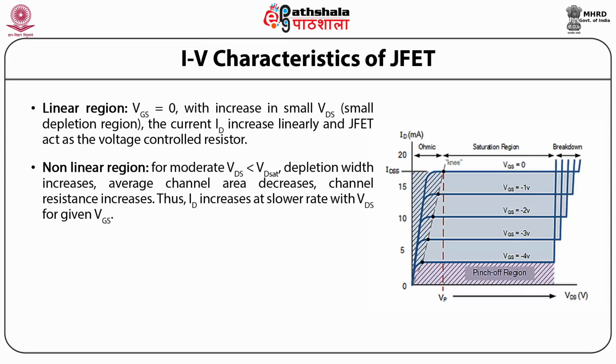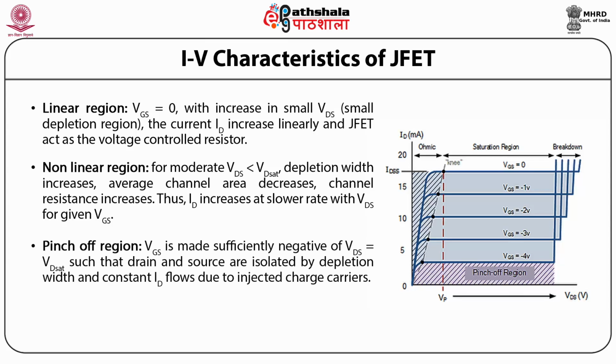So, next is the pinch-off region. It is nothing but a point where there is a pinch-off condition. VGS is made sufficiently negative, with VDS equal to VD saturation, such that the drain and the source are isolated by the depletion width and a constant ID flows due to injected charge carriers.